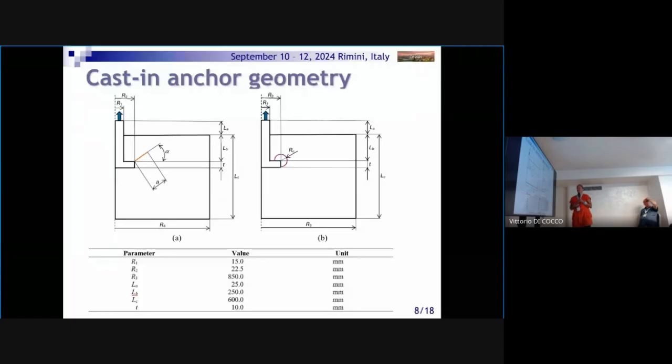You can see the specific lengths of the parts of the model, and we varied three parameters: the crack length, the initial crack angle, and the radius where we investigated the stress distribution.